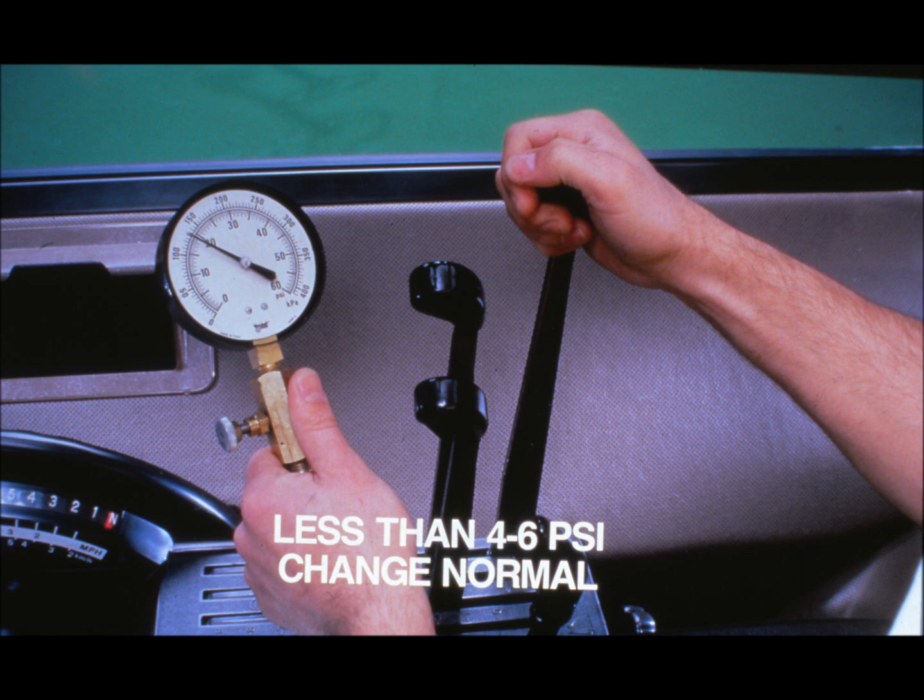Record lube pressure while the SCV is circulating oil. If lube pressure has dropped by less than 4 psi at 150 degrees or 6 psi at 100 degrees, the system is normal. Proceed to the next step. A greater drop in pressure indicates a leak from the return circuit to sump.